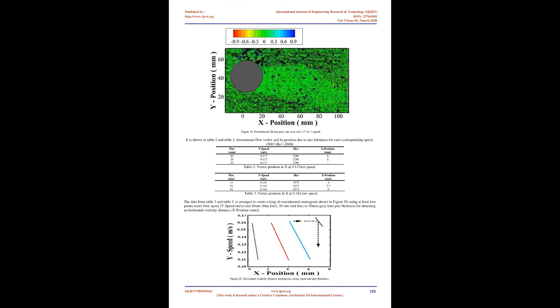Conclusions. Using LaVision DaVis 8 video software processing and post-processing with Tecplot 360 software, it was possible to obtain images of the study areas in 2 dimensions, flow profiles. In the upstream study area location, the flow through the slimmest pier showed a linear trend behavior, generating a moderate small vortex, and for the next 2 piers, the flow tended to hit the bottom, increasing its vorticity and going further back a long distance at different positions.